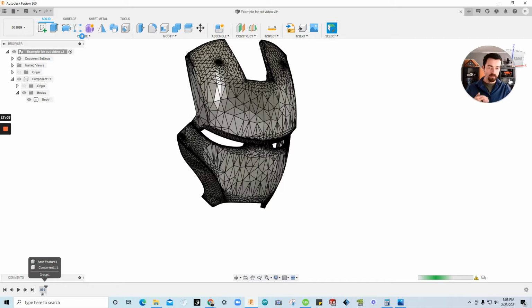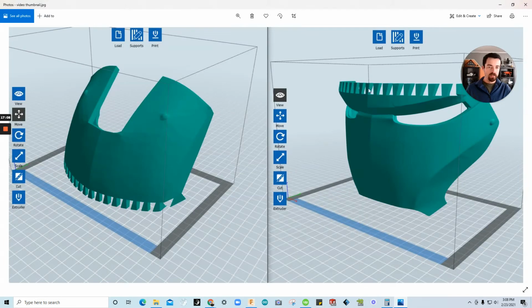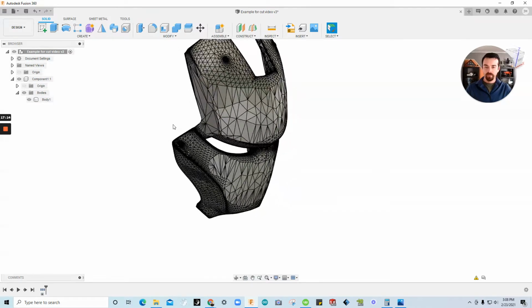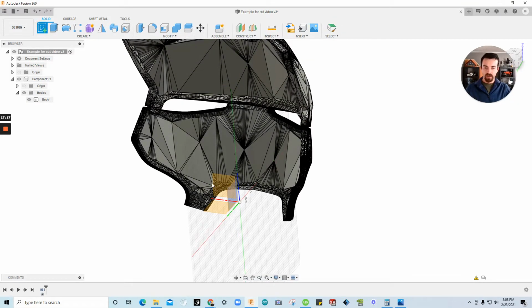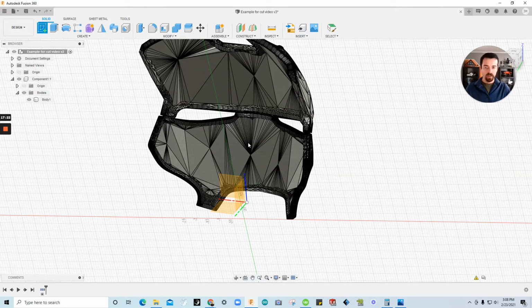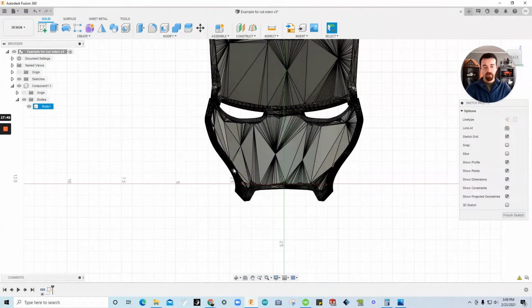So you want to make a custom feature. What I showed you earlier is what I want to add, which is the dovetail features like this, and let's jump into that. So first thing you gotta do is sketch. I'm going to pick a plane that looks to be about parallel with the part of the body I want to cut, and when I turn on my origin over here, because I already clicked sketch up, I'll click escape, show you what that looks like. I could click turn on the origin, or you can click sketch and your origin will automatically become visible. I'm going to select this face because it will allow the sketch to cut through when I extrude the sketch.